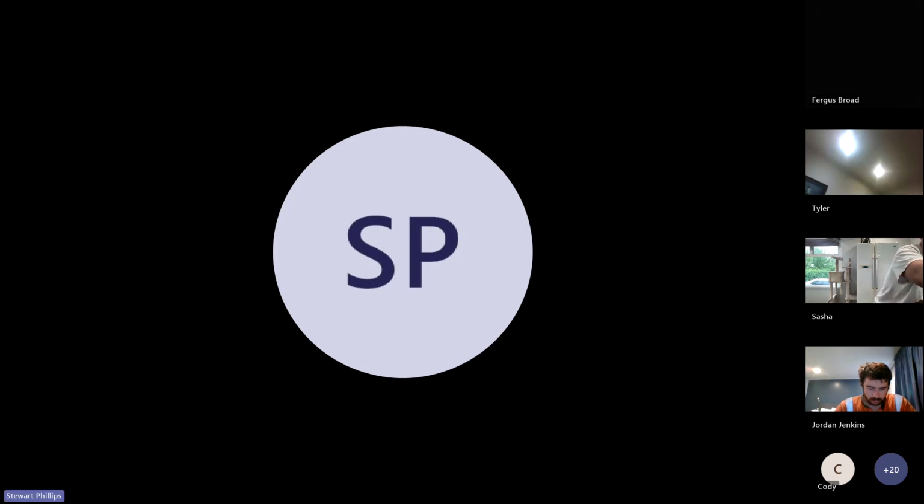Yeah, so the majority of you are on the right track. A fuse is single use. The fuse element melts and needs replacement after a fault. An MCB can be reset manually after tripping, offering reusable protection.